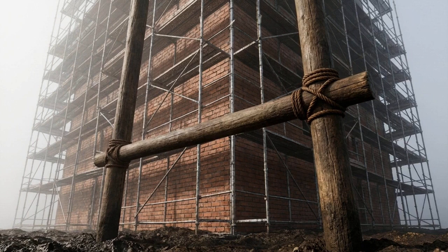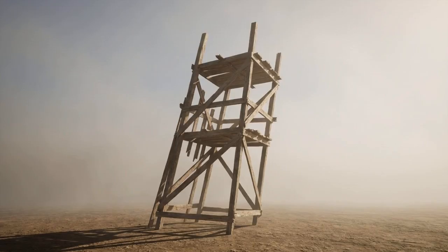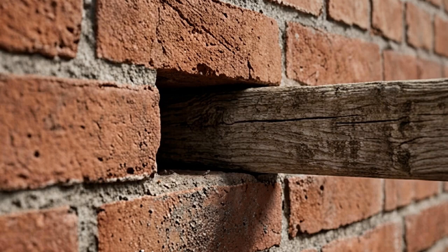Down at the base of a traditional brick wall, the foundational anatomy of a scaffold begins with two primary elements. Vertical posts, or standards, rise out of the ground, connected by longitudinal horizontal pipes known as ledgers. But the traditional bricklayer's scaffold has a severe structural constraint. It cannot support its own weight. To remain upright, the entire framework must physically lean its weight into the host building.